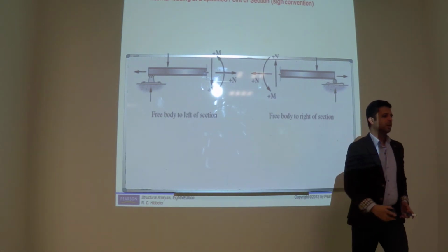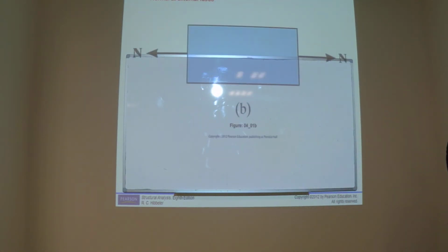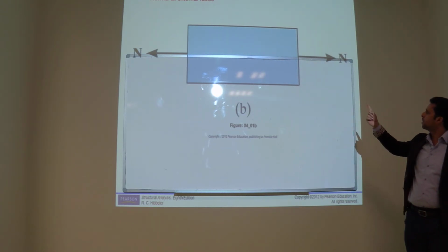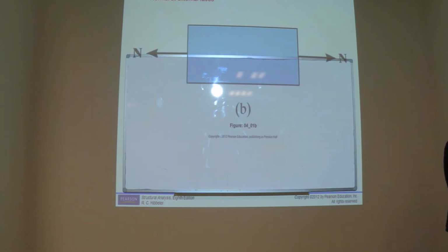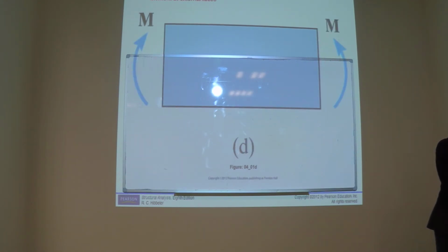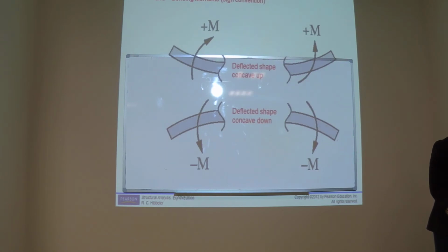Okay, let's go next. So, will this normal force be positive or negative? Positive. This shear force, clockwise, positive or negative? Positive. This moment, positive. Now tell me, now you can see the sections, left or right.